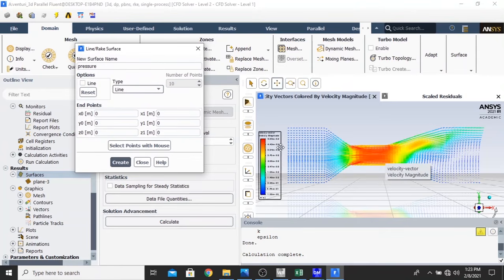If we remember, in the sketch back there, the start of the sketch is at the 0 position of the X, Y, and Z axes, which is in the middle or center line of the inlet. So I want to draw the line exactly in the middle or the center of the surface area of the inlet until the outlet in the diverging part surface area.